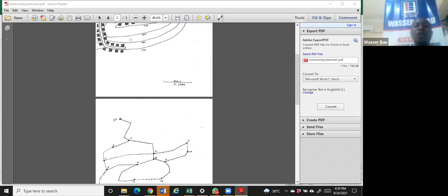Okay, you say node 2 is not looped. That looping is if you are using a loop system. We said there's a branch system and a loop system. So the dotted line is assuming you are using a loop system. It means you now continue with that line. And in this case, if you do a branch system, what you do there is provide a valve there, a closed valve there.